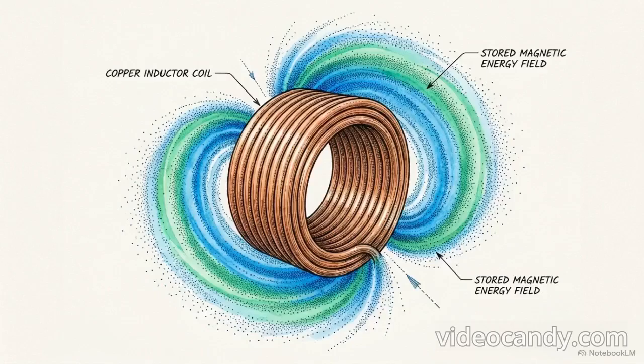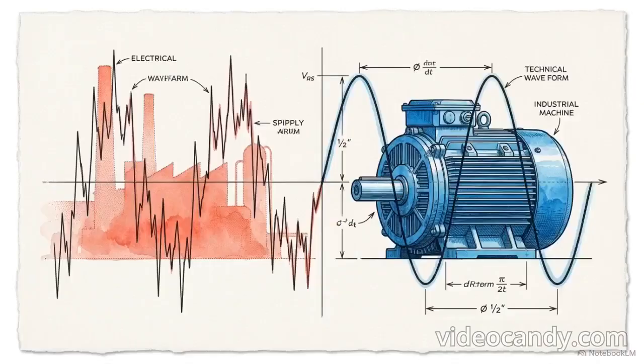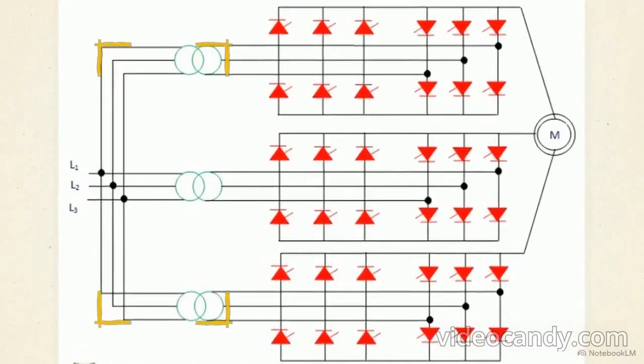To prevent the cycloconverter from shorting itself out under these conditions, the firing circuits must be aggressively reprogrammed. The controller continuously calculates the phase angle and delays the thyristor gating pulses to match the current lag. The physics of inductive energy storage forces a significant delay in commutation, requiring the control system to continuously calculate and compensate for the resulting phase lag. Single-phase cycloconverters prove the switching concept, but a single phase produces pulsating torque. Heavy industrial machines require smooth, continuous power.